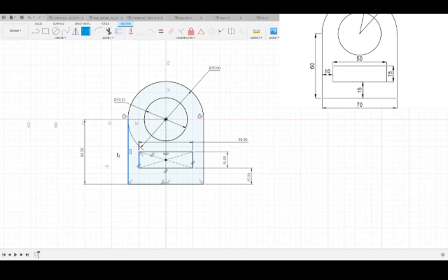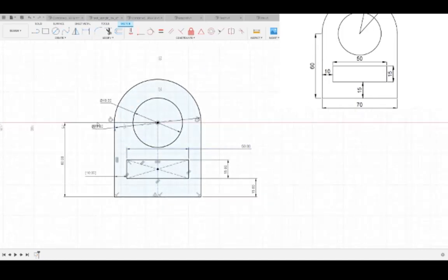And as you can see, because all these dimensions are already preset, if you add another one, you're going to over constrain the sketch and make it a driven dimension, which basically means that the outside parameters are what define that dimension, rather than this dimension or these dimensions defining other parameters, if that all makes sense. So that's a driven dimension, and now our sketch is complete. I'm sure that was a bit of a mouthful again.